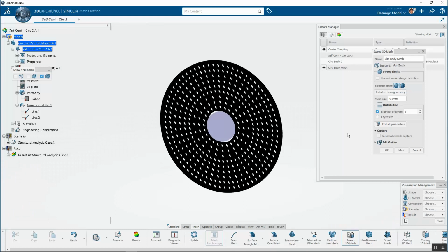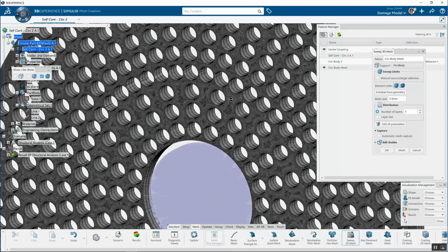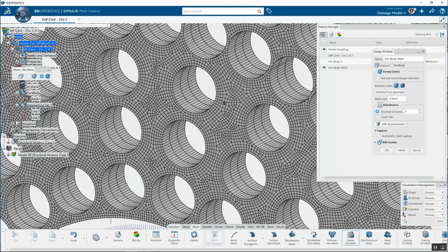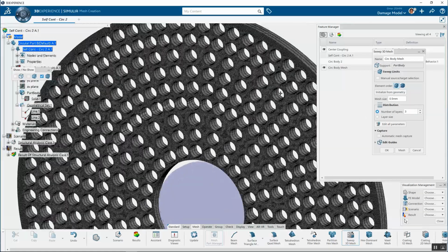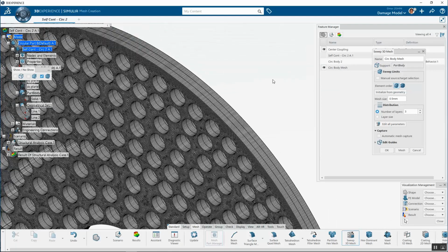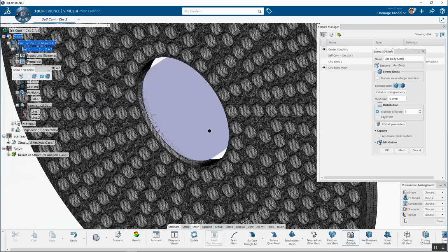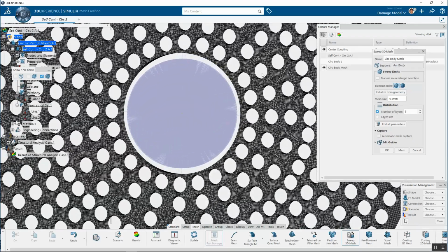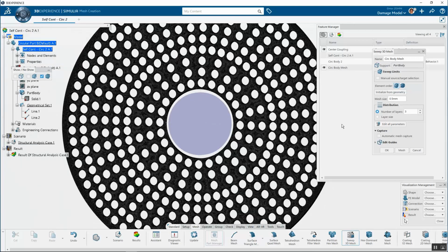where you could walk through and look at the settings for each individual part. So you can see for this guy, I'm using a seed size of 0.5 millimeters. That's basically saying these elements on the face are about 0.5 millimeters, and I'm saying I want 3 elements through the thickness. And you can see we've got our 3 elements through the thickness. So obviously I've got full control over that. There are some really fancy things that you can do if you want to have more control over your seed mesh, your face mesh before you extrude it through the thickness.